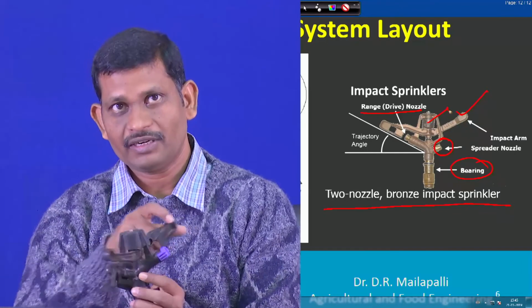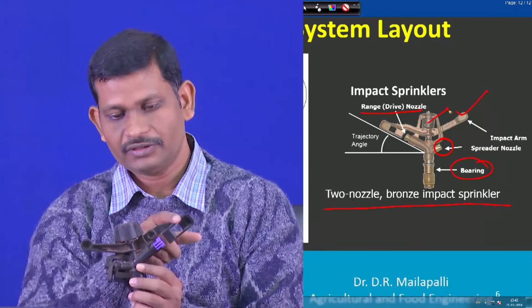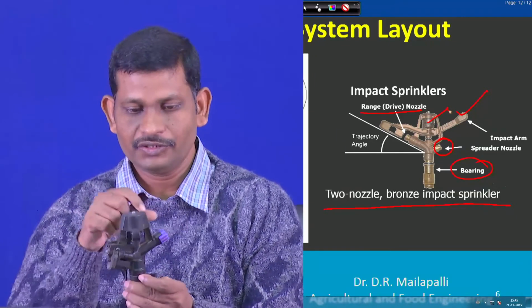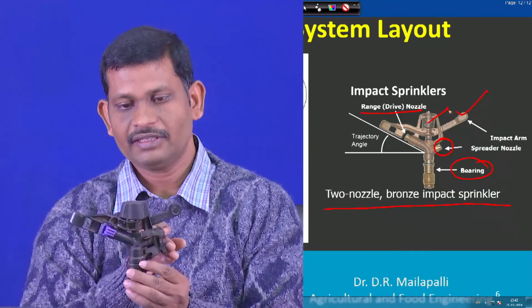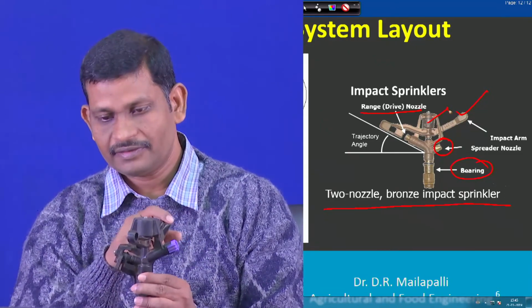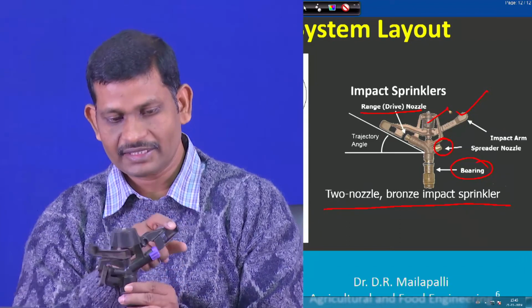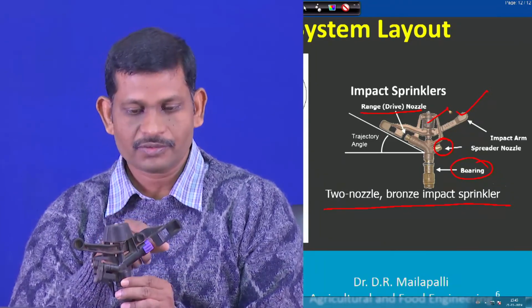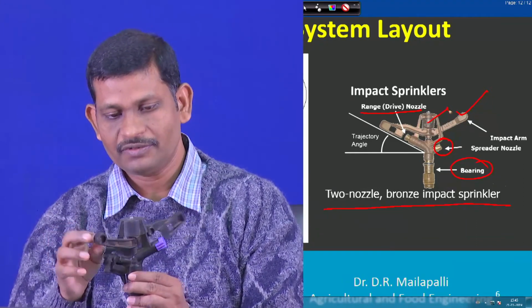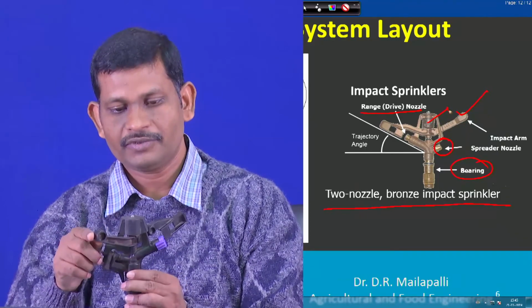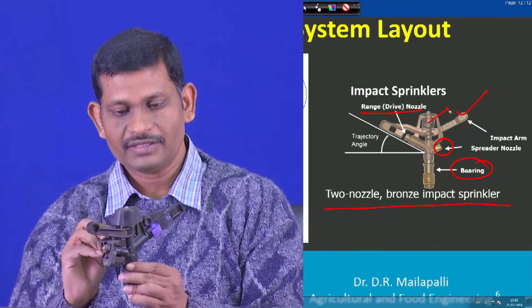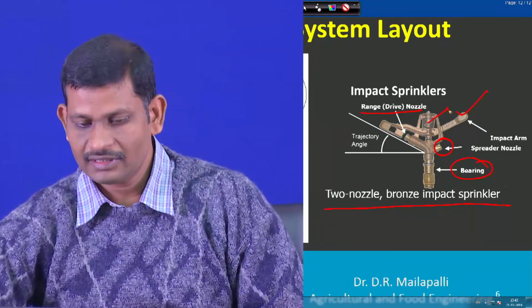So, it is like one by one, right, 1 2 3. Similarly, since it is a moving head, for each impact it is going to move, like this. Okay. So, it's both ways. The arm is going to split the nozzle, and at the same time this is basically the counterweight which brings it back, and the spring and counterweight help in bringing the arm back, and with that impact the whole head is going to move slowly. So, this is the mechanism.